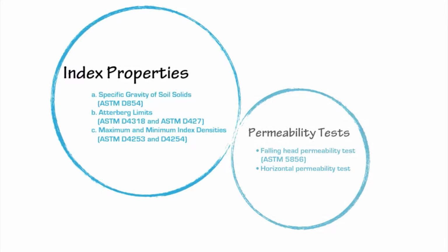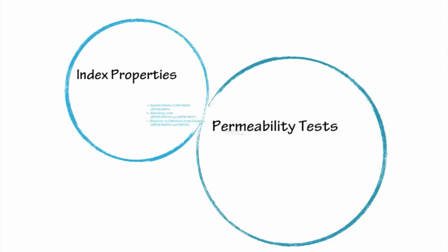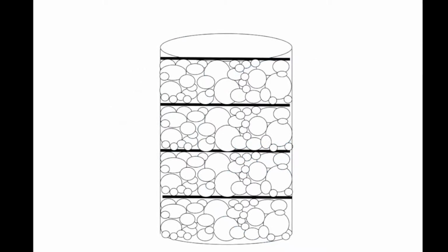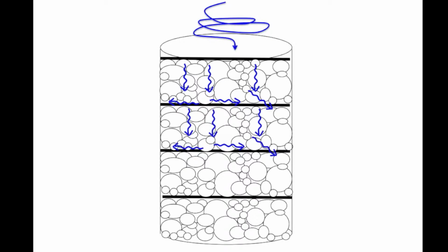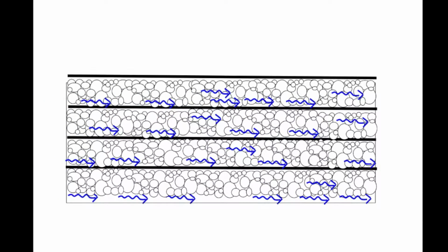In this study, the researchers follow the ASTM standards in order to determine the index properties of each sample. For the highlight of this study, which is permeability, the researchers followed ASTM 5856 for the vertical permeability. Another thing about permeability is that when it goes through the said surface layers such as concrete or asphalt, it does not only permeate downward but permeates in the horizontal direction. But since there are no ASTM standards for this, it led the researchers to design the horizontal permeameter.